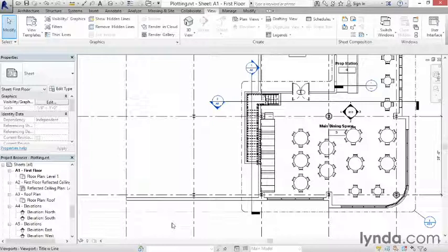And once you get the settings the way you want, a nice, unique feature to Revit is you can save not only the list of views and sheets that you're printing for future use, but you can also save all the settings in the page setup dialog for future use. And that makes your work in there that much quicker the next time.